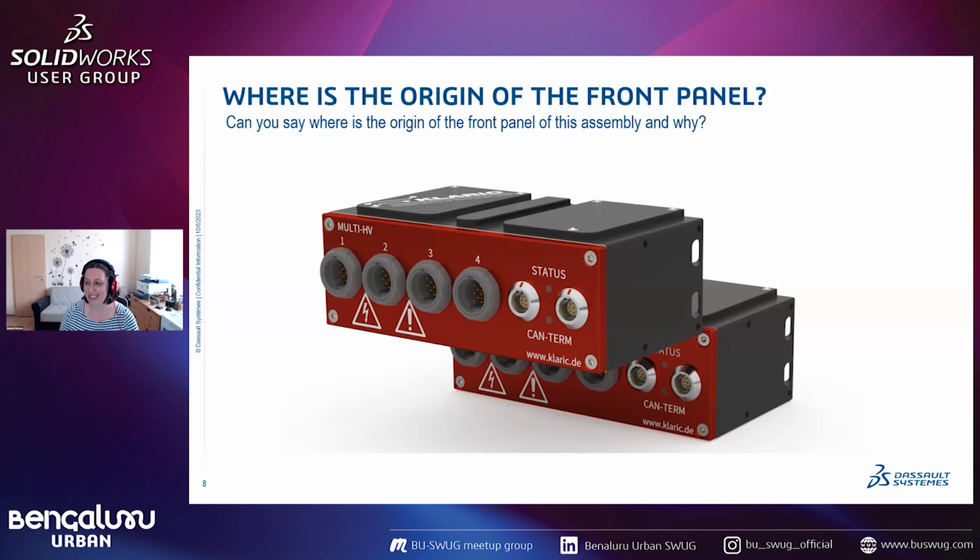Okay, you give a good reason, but to be honest, I was misleading you a little bit with this question, and I will tell you now why. I'm asking you this question, but you don't have enough information to give me the origin of this part. You guessed it correctly. The origin is in the bottom left corner, but usually, if you are following just the design logic, it should be in the middle left, because the middle left is where the connectors are. And when you have something symmetrical top and bottom, it's good to be on the origin. That's the design logic for the origin.